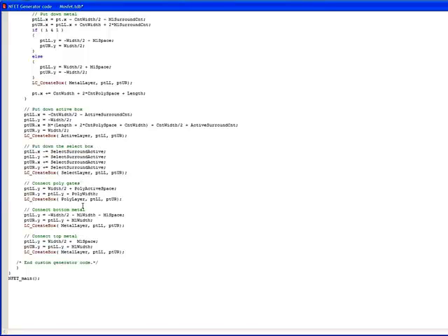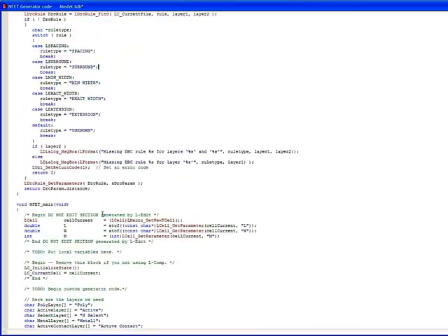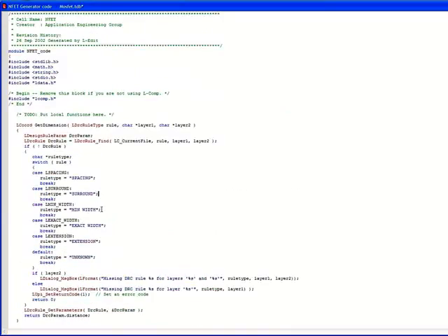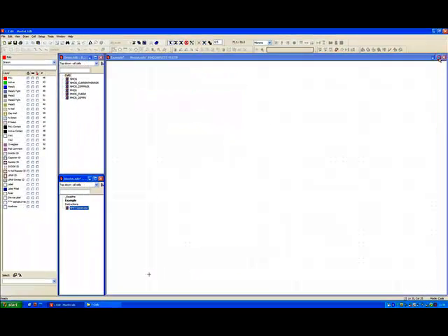So anytime a company wants to move to a new technology node, they have to invest this upfront cost in coding their parameterized cells, or certainly developing their parameterized cells. However, obviously for this once-off cost per technology node and per tool set, what it does give you is a very, very accelerated full custom layout flow.